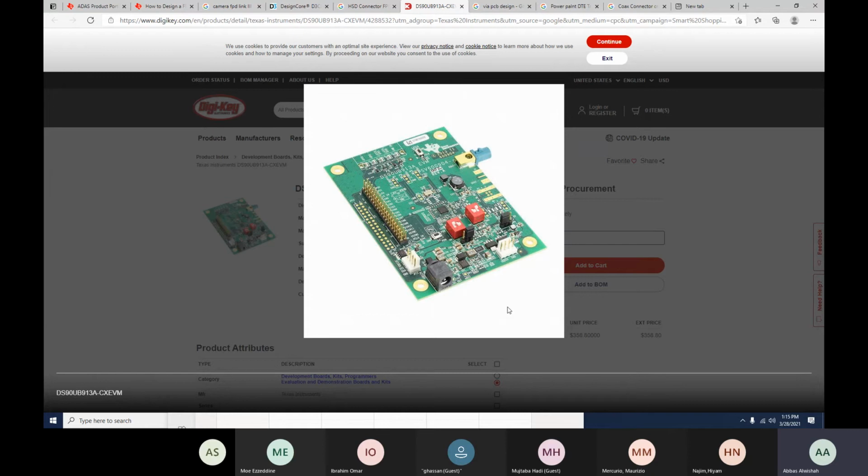All you have to do is walk on carpet or have a sweater on and the heat is on. And guess what? If you touch this board without touching the ground pads, what happens if you're touching the micro? You just sent all of the electrostatic discharge, ESD, all into this micro. You've blown it probably 9 out of 10.